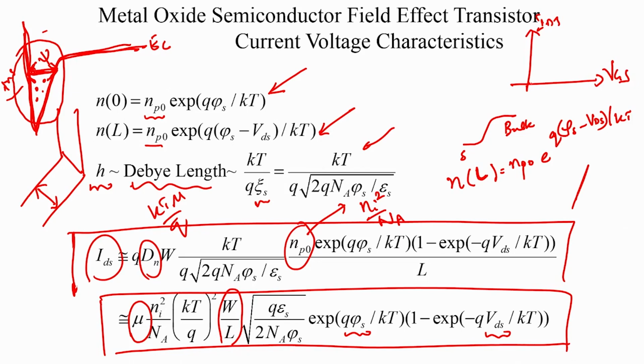Let us say below flat band the currents are all ignored, and between flat band and subthreshold we will no longer say that the current is 0, because we now have an equation here. We know that the current is exponentially increasing, and then beyond Vt the current enters the square law dependence on the voltages. So, that is the current voltage characteristics of the MOSFET.